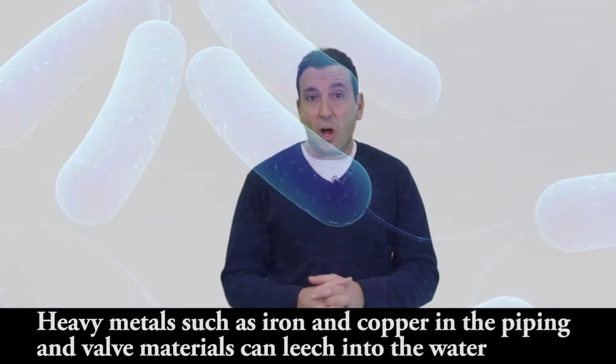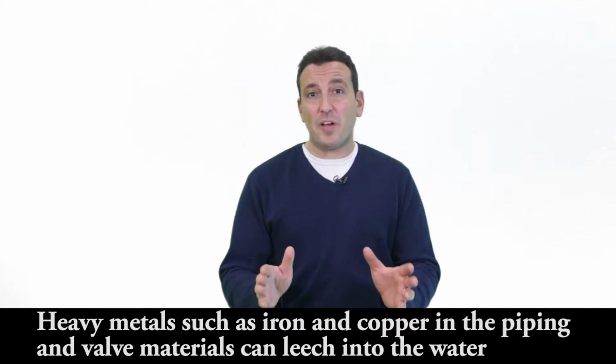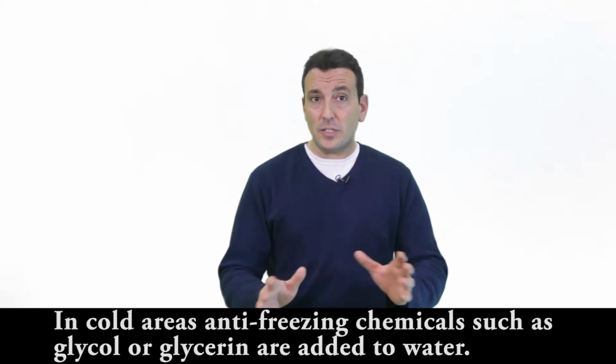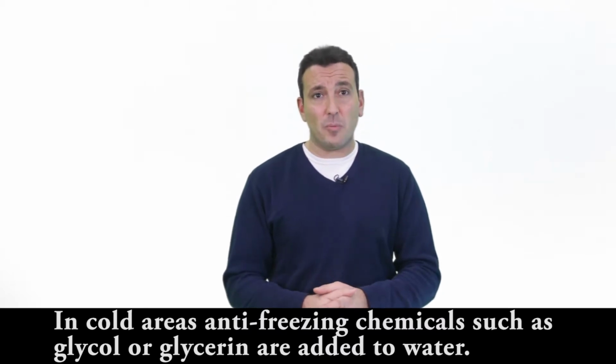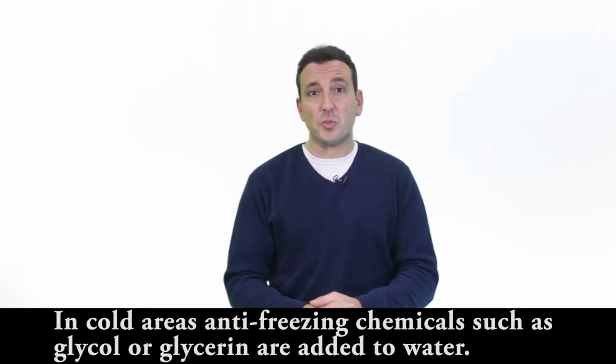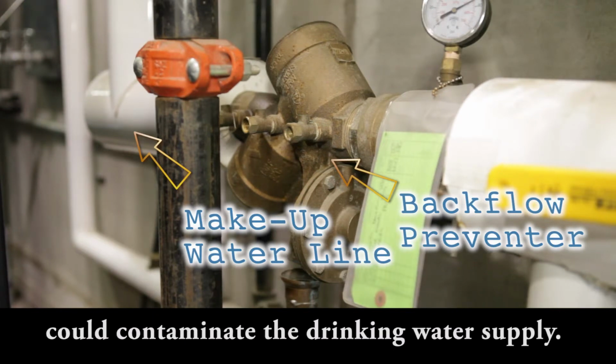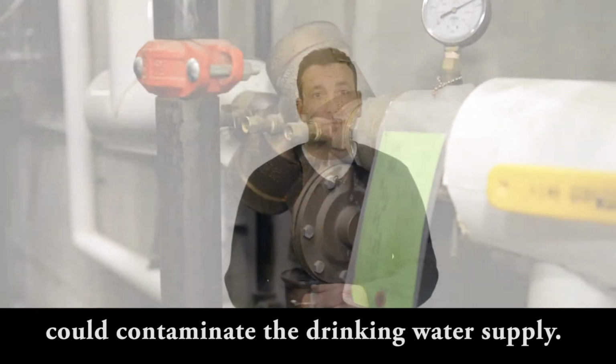Heavy metals such as iron and copper in the piping and valve materials can leach into the water. In cold areas, anti-freezing chemicals such as glycol or glycerin are added to water. If backflow happens as a result of a fire sprinkler system, the deteriorated water can contaminate the drinking water supply.